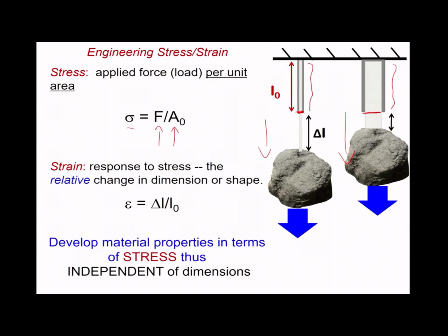Okay? And then of course we can measure experimentally what this elongation is going to be when we apply this load by just measuring the delta L, right, that change, and then we take the change divided by the original length, L naught. It will give us the strain, right? It will give us our x-axis, and we can calculate what our y-axis is in our stress strain curve. Okay, so this is obviously just a schematic of these types of experiments.